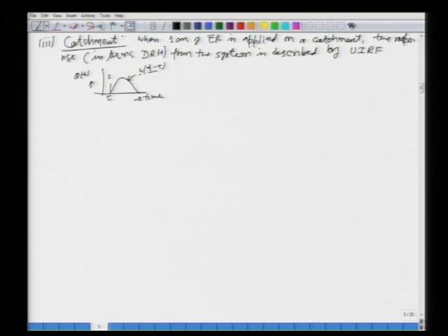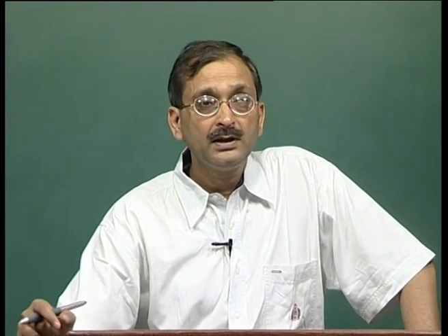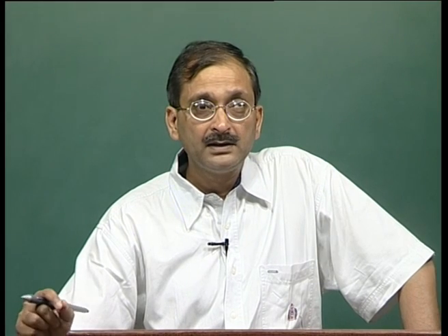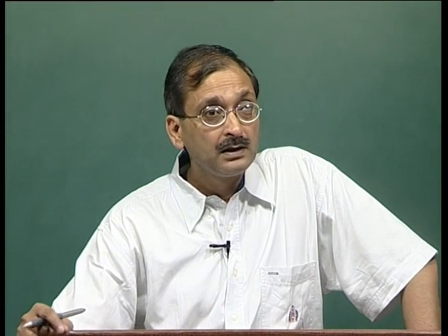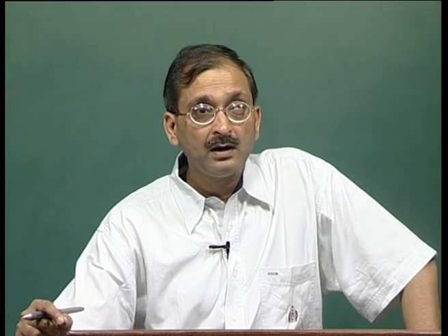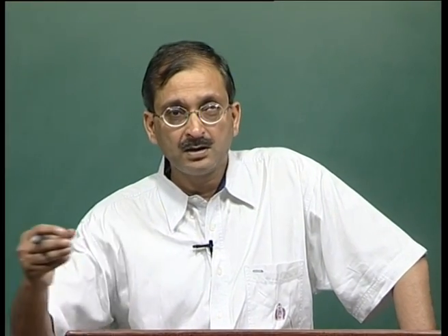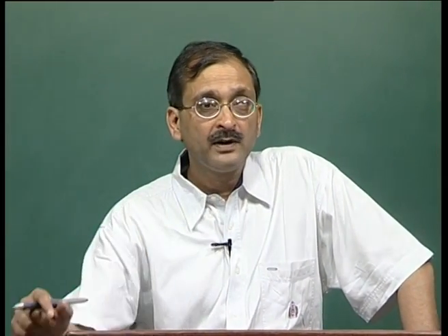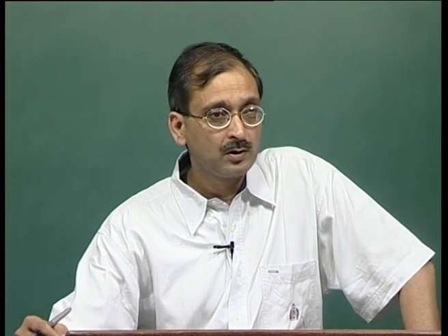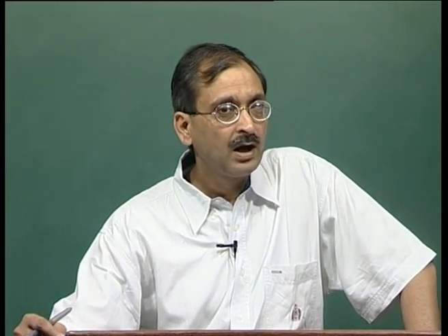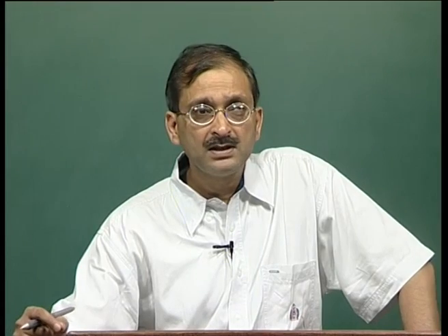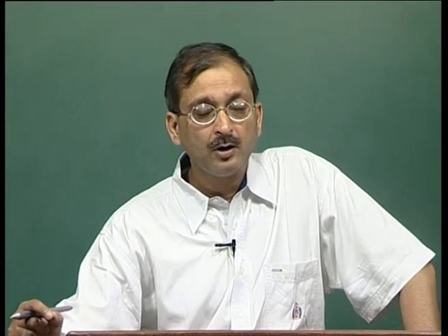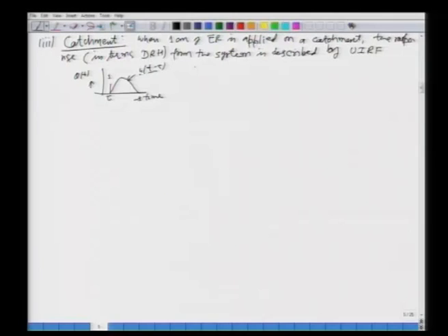Now, this input which we have seen is instantaneous. The way the unit impulse response function is defined is that this 1 centimeter of rainfall is applied instantaneously. However, in reality the rainfall does not occur instantaneously. It takes some time, for example a certain amount of rainfall occurring in 1 hour, 2 hours, 3 hours and so on. So how do we find the response from a catchment using the unit impulse response function for a continuous input?